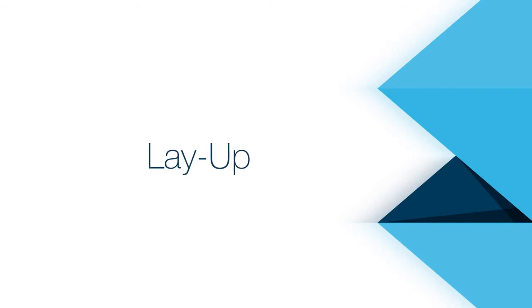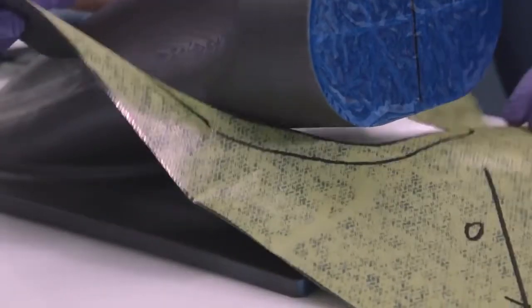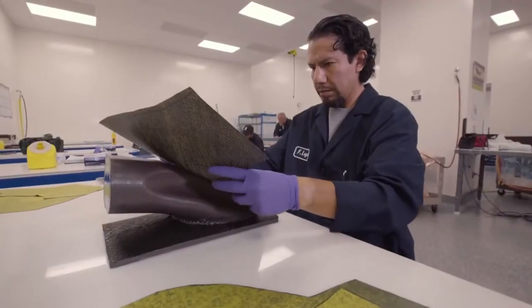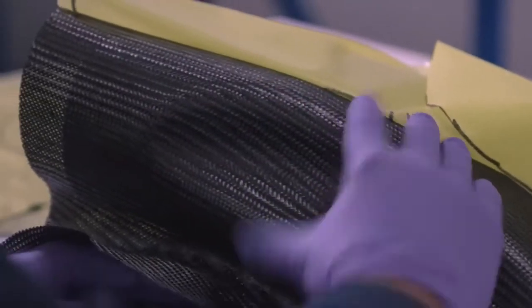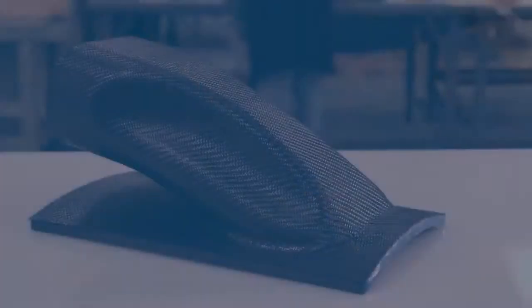The part lamination process begins with ply development, where the technician creates patterns according to the geometries of each part. That allows the composite material to drape properly, to give the right fiber orientation, and to maintain it. That process is very tedious and very important.